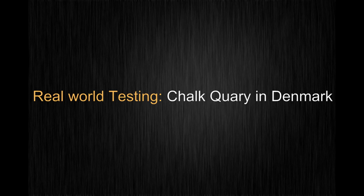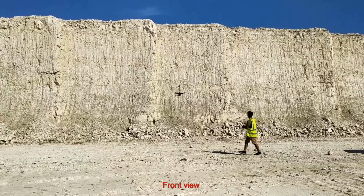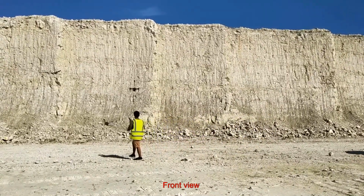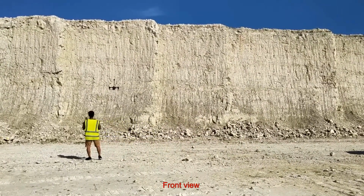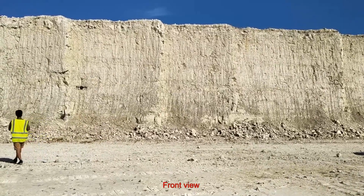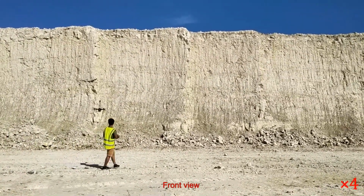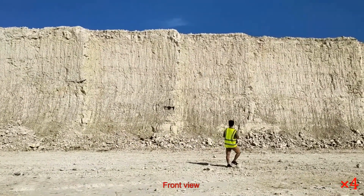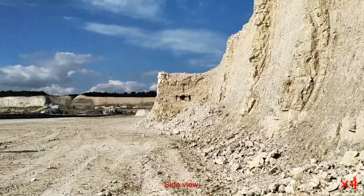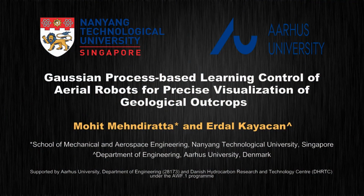Next, we tested the algorithm in a chalk quarry located in Aalborg, Denmark. Again, the robot starts with conventional NMPC and switches to the GP-NMPC framework after the GP model gathers the required data. The real-world tests also exhibited an improvement in the tracking performance of NMPC due to the GP-based disturbance learning. Moreover, the robot is seen to accurately track the trajectory command from the navigation algorithm. For more details, please refer to the paper.